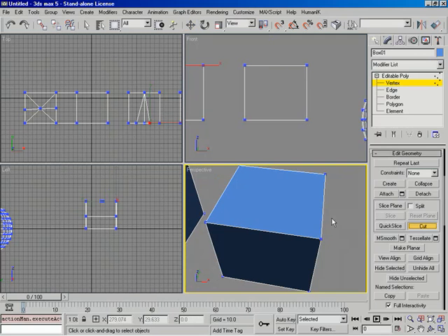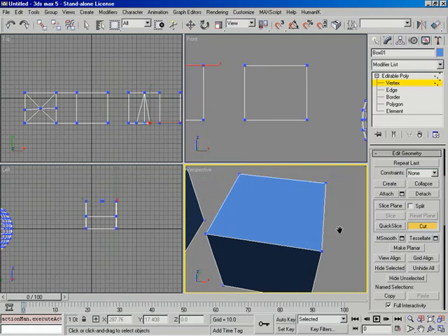So how does it work? Oh, this is so simple. Let's go ahead and just move that down a little. I'll click starting from this vertex, and it's already making suggestions. How about we cut this way? How about we go this way? Because of full interactivity, wherever you move your mouse, it'll make those suggestions as to where the cuts will go. And it's going to show you these edges. And if you turn it off, you're just going to get the old dashed line. So full interactivity is absolutely awesome in this case.